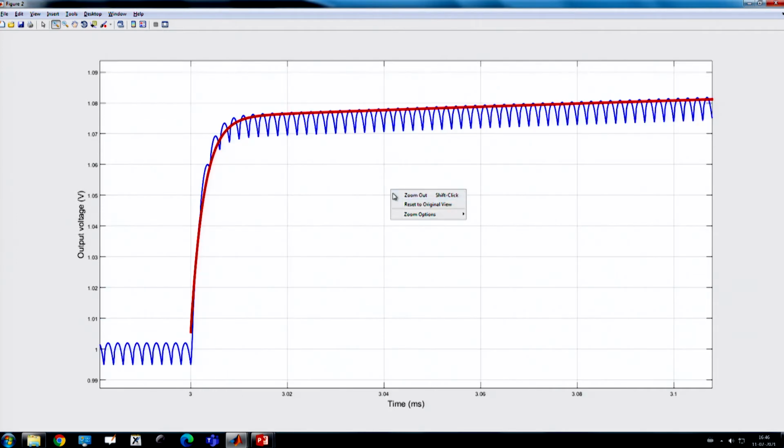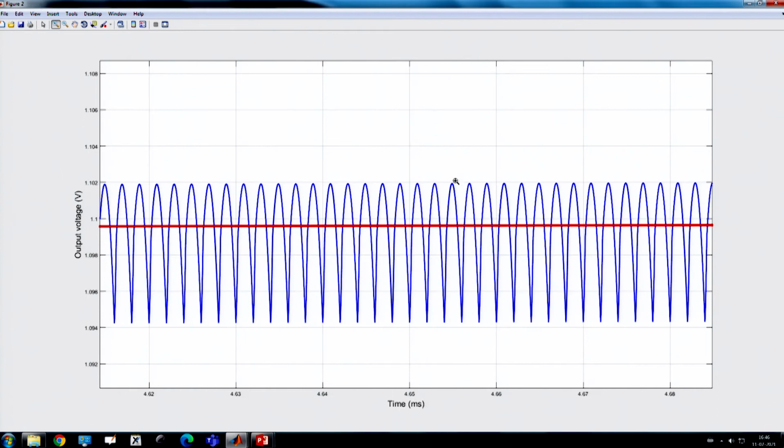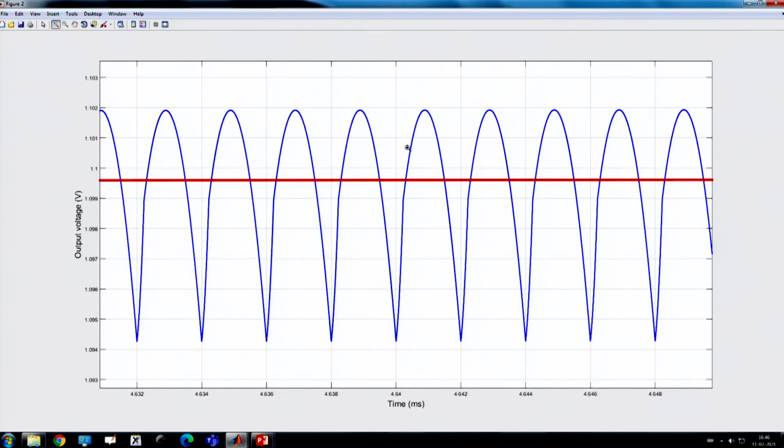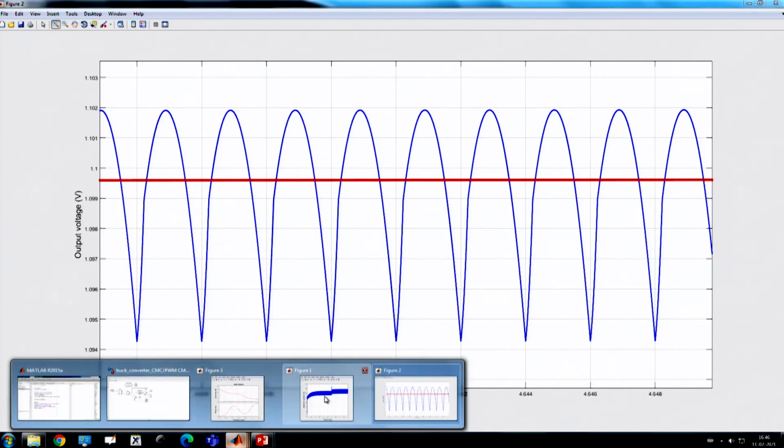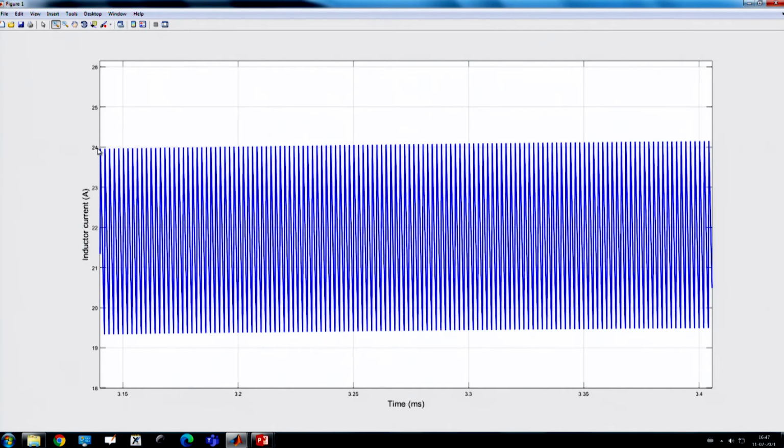That means now you can see the DC matching is close, because earlier the mismatch was due to our initial assumption. We had taken the control current equal to the average current, which makes sense when the load current is high, because if you go back and see here, your peak current is 24 ampere and average current is 22.